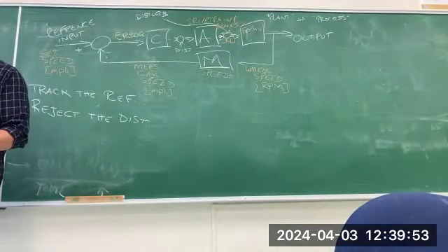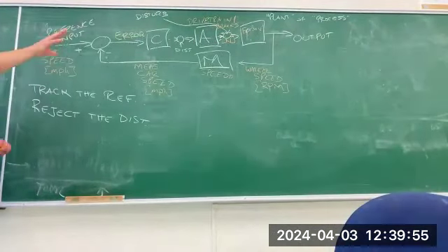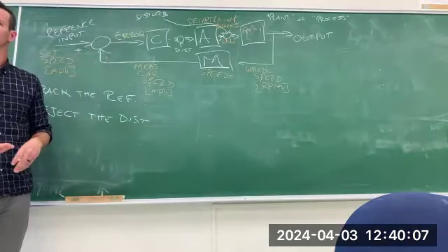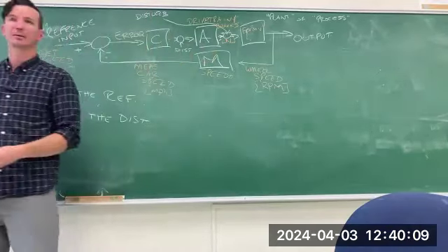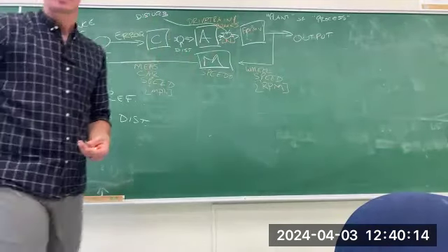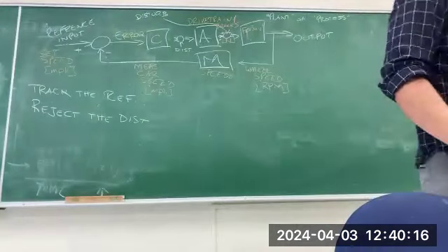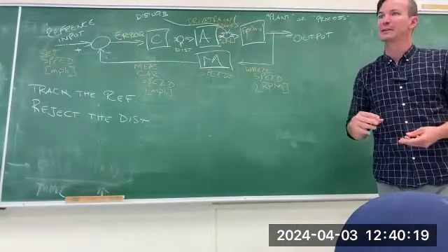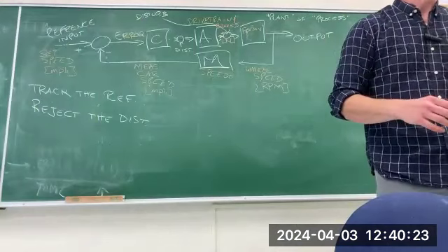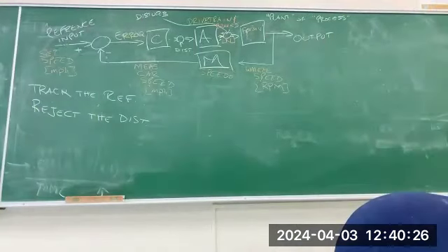Functional or abstract block diagram is basically saying what are the major important subsystems and what are the signals that travel between them. We're not making any assumptions about LTI or Laplace or anything. We have a speedometer. It changes real speed into sense speed. That's it. And the next steps will be something like take that functional block diagram and dive into it and try to model it with your physics and your math knowledge. That's where I'd like to go now.